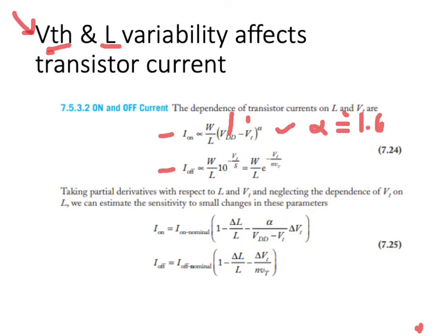So as we minimize the technology, the transistor gate lengths, mobility saturation and velocity saturation reduce the effect of the gate voltage on increasing the current.